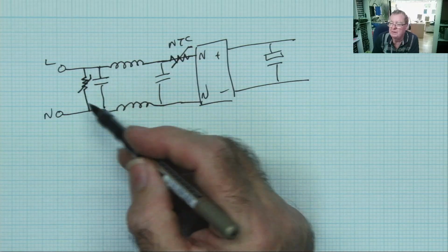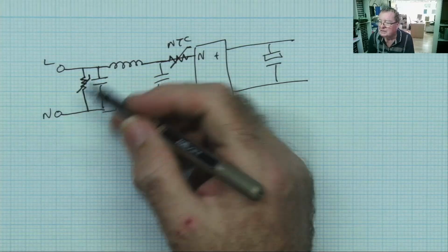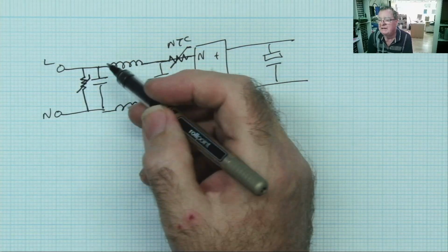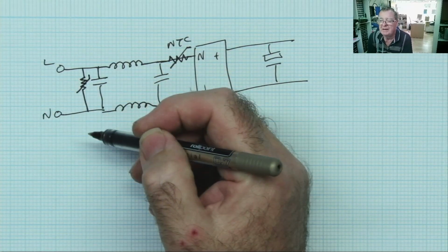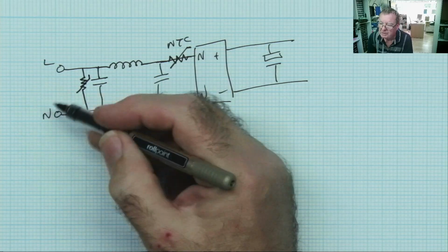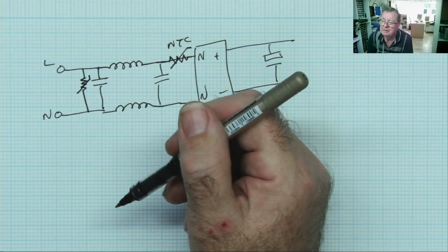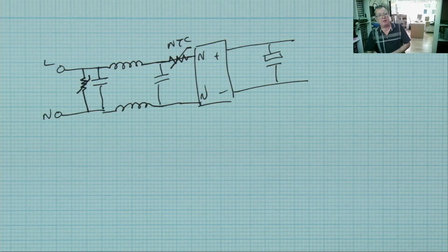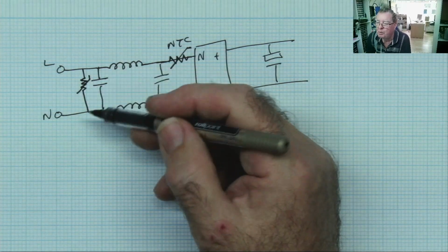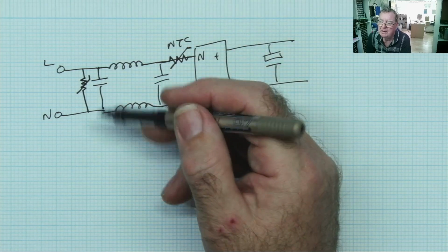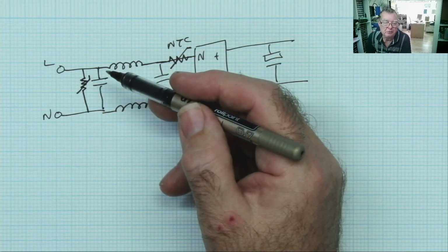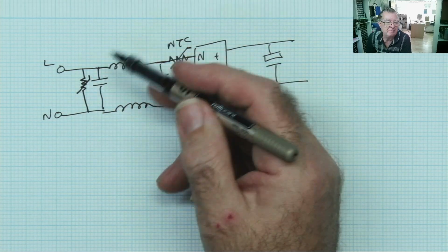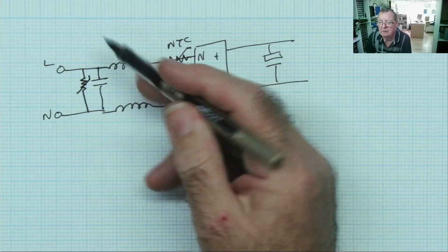You can look up the part number. If this is exploded and you can't even read the markings, you can normally work out. So if you know the input voltage, you can usually work out a suitable component to go in there. And you don't put one rated at the input voltage. You'll often find for 220 volts, it might be 275 volts or even 400 volts, okay?